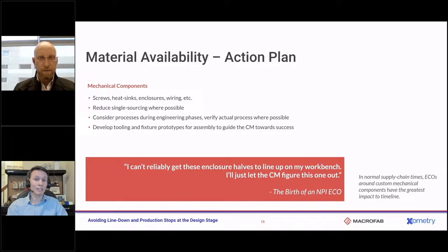I will also say something interesting that I used to do in a previous life was testing the physical fit check with additive manufacturing on the PCB, like literally making just a plastic mock-up of the PCB. And you can do some tricks of the trade if you're able to export a 3D model, where you can essentially just thicken the PC board a little bit so you have overlap, and then you do a Boolean combine, and now you have a solid piece that you could then 3D print, and it can actually tell you some stories.